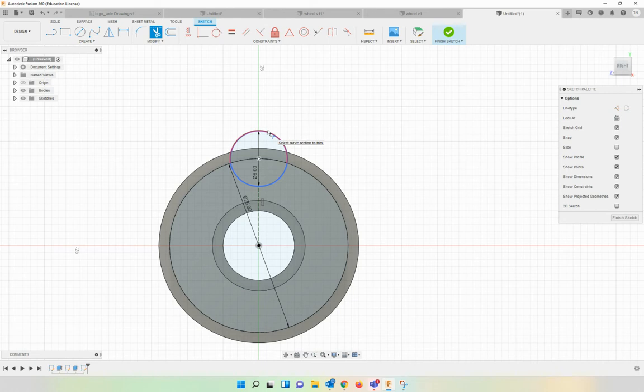There's the shortcut there. And notice, it's intersected by this circle here. So when I hover over it, only the part above that intersected circle turns purple. And if I click, it cuts it away. Escape out of the trim tool, because that's exactly what I want there for my design. Now, I need 5 of these circles. I could draw 5 more, but that would be a bit of a pain. I'd have to work it out mathematically, measure it, get it all worked out on how to position it. Fusion gives us a tool that makes this incredibly easy.